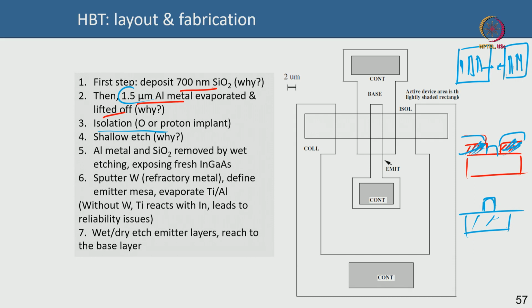They should not communicate. In FETs, for instance, you often do a mesa etching, but here you can actually do an implant. It can be a proton or an oxygen implant, and you will make the area where you implant insulating, so that device number 1 and device number 2 cannot have crosstalk. They cannot communicate with each other. Okay, so this implantation is done to separate the devices, and for this implantation you need a mask.